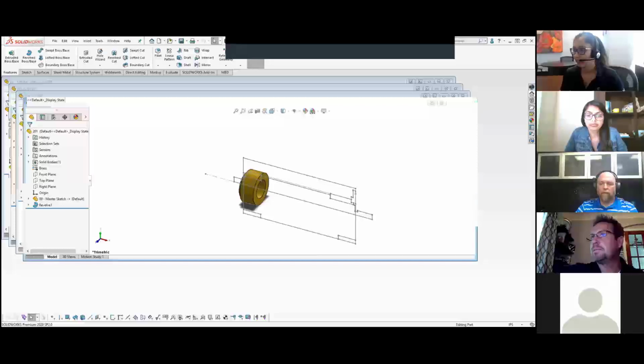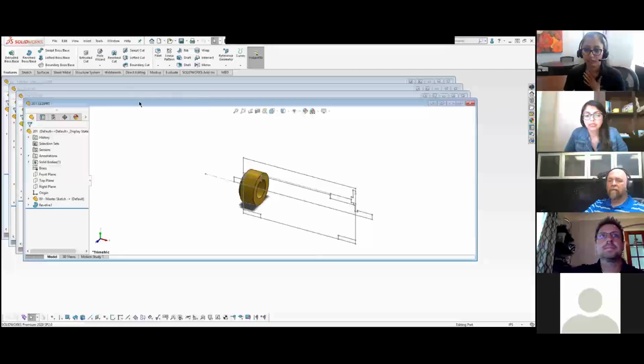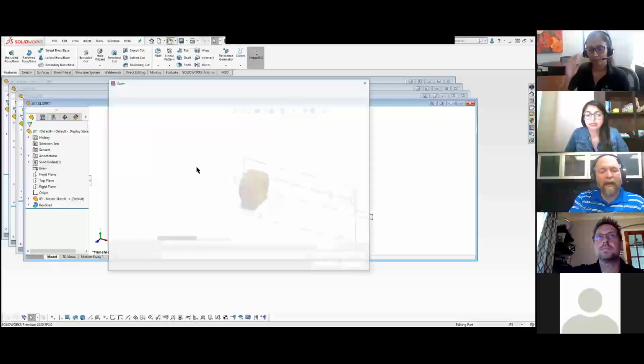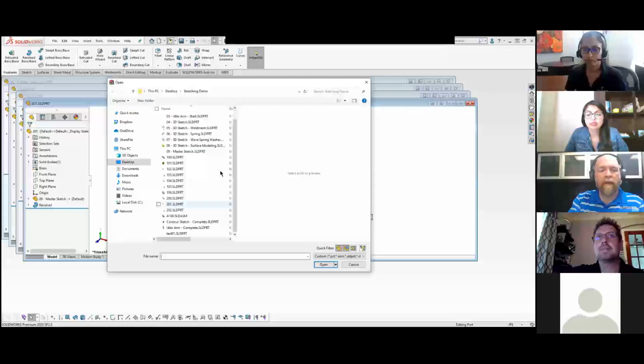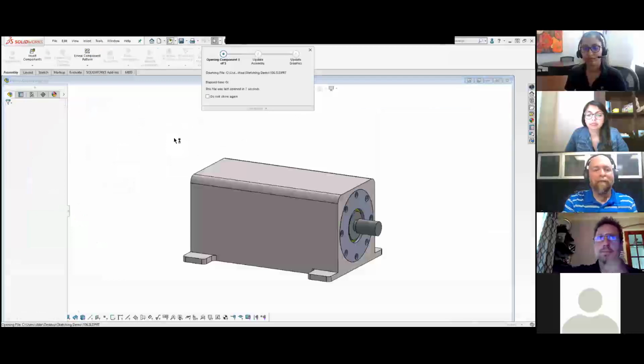Somebody asked, well, the next one on the list was, is it best practice to ensure all sketches are defined, or are there scenarios where underdefined sketches would work? Technically, you can always have underdefined sketches, but we really recommend, or I really recommend, defined sketches. I think having a fully defined sketch is just going to prevent you from accidentally missing that human error aspect, right? If you're underdefined, you can't predict what's going to happen if you change your part. So that's really the big kicker. If you don't care where parts go when you modify them, don't define them.